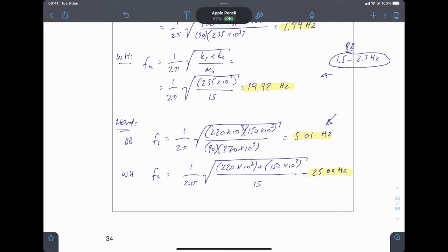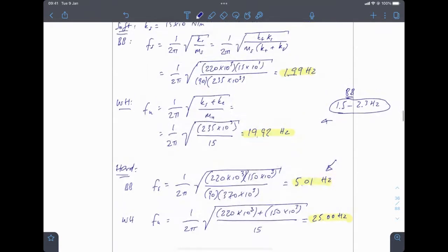So it's quite important to get the frequency right for ride comfort. And like I said, that 5 hertz is supposed to be okay for a racing car with stiff suspension, but it's not so okay for road cars. That's also the advantage of having air springs, because you can tune this to be what you need it to be, and it won't be affected by the mass on the bottom, because this is for standard coil springs, not for hydropneumatic springs.